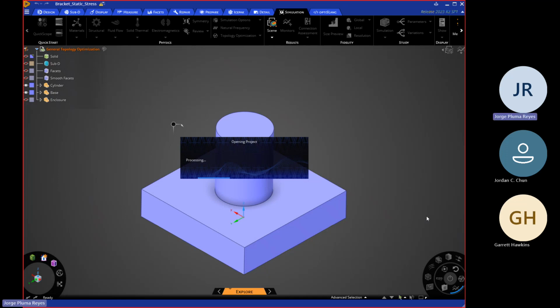And the idea is that I obviously don't want to use this, because this would give me the maximum stiffness, maximum reduction in stress, right? We have this big piece of aluminum just encasing our whole problem. The problem is that often that's not the ideal approach because you're just adding a chunk of material, and the idea is to try to make this lightweight while still serving the purpose of reinforcement, right? So if I bring back my cylinder and base, I can visualize the problem again.